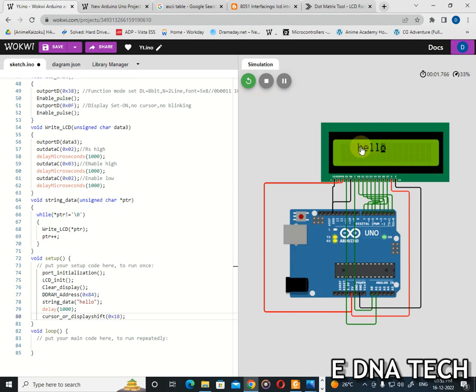Here you can see the display is shifted left by 1 bit. The cursor also moves to the left depending upon the display shift. We wrote the value H at the 5th position, but the hello is now in the 4th position. So the display is shifted left by 1.